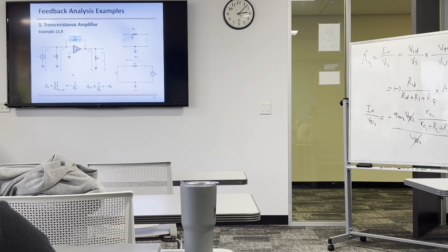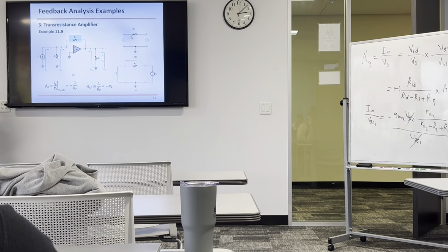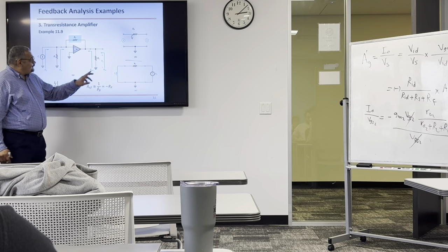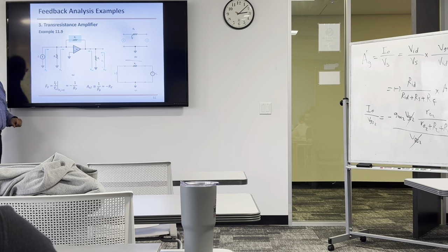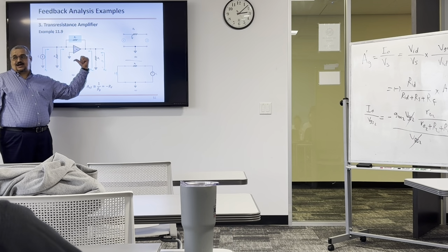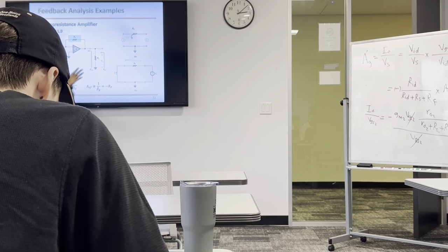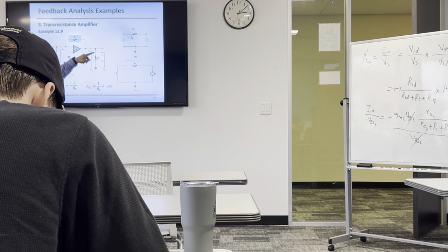Any questions? So, say for example, we had something similar to this one, right? This one? Yeah, where we had VO on the resistors for the previous, then we would actually have to make it parallel. Can you say that again? So, for example, this one that says VO next to RL, right? Yeah. If the output quantity is a voltage, then you need to look into the circuit from a voltage point of view. So the voltage takes things in parallel, right? But if it's the current, then you have to cut and see how the current sees the resistance in the loop.